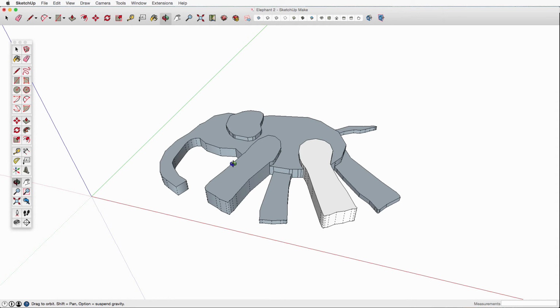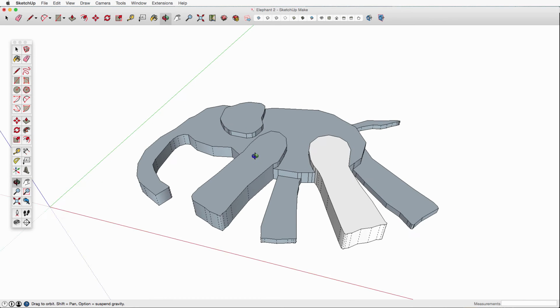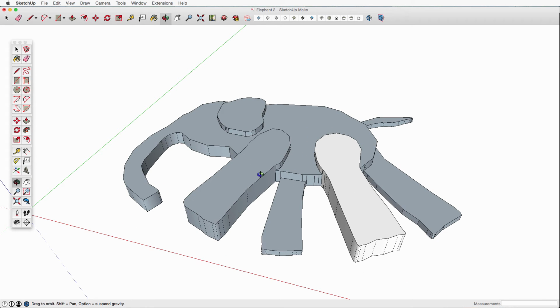And there's a couple different ways that you can do that, but one of the easiest ways is to use the push-pull tool again. So press P, and you're briefly going to tap Option. And you can see down at the bottom, it says Option equals creating new starting face, which sounds complicated, but if you tap it, click, and then bring it up, you'll see that it actually has a different section for us to work with, which is important because the next step for us is I pressed S and then clicked on that surface again, and we're going to shrink this down.